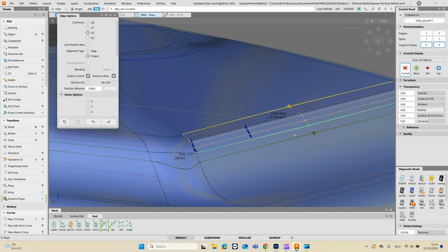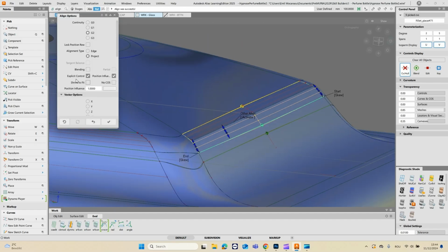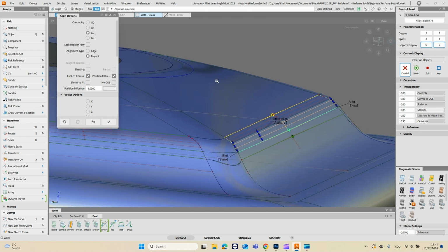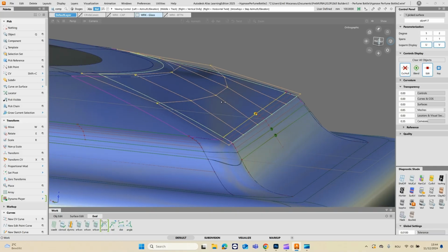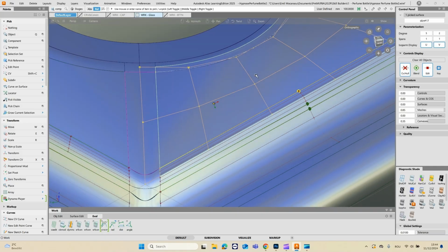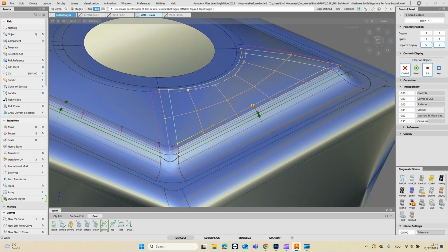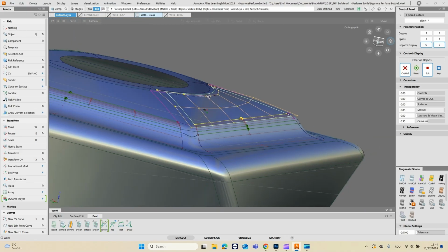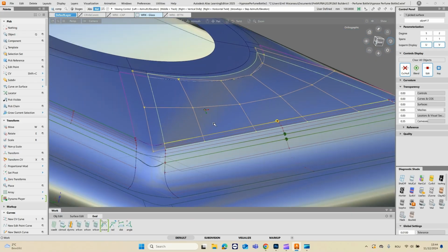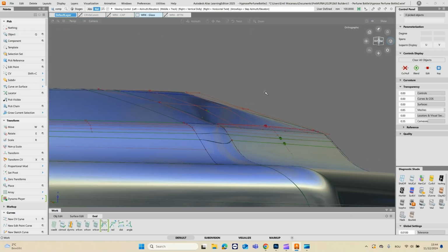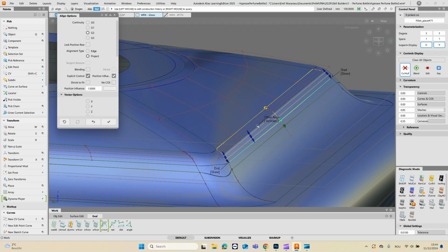And then on this side, same stuff. See, this is a simpler surface. This one is a bit more difficult to handle. And the reason why it's doing that, it's got a twist in it. It's twisting and it's connecting from a straight edge to a round one. So this is pushing that. It's driving that shape and it makes it a bit more complicated. But a few more CVs on the length of it will take care of that problem.